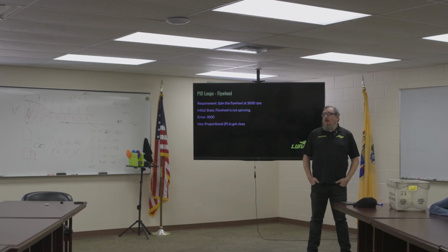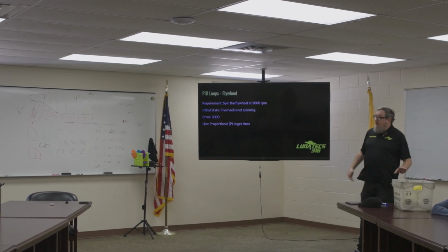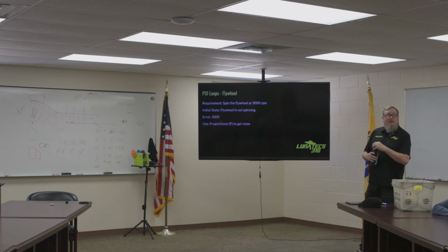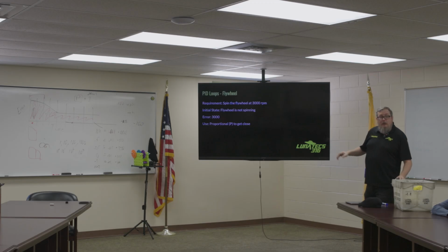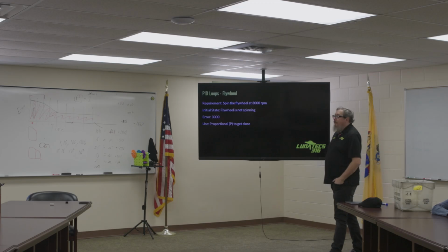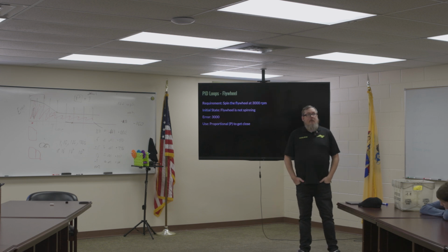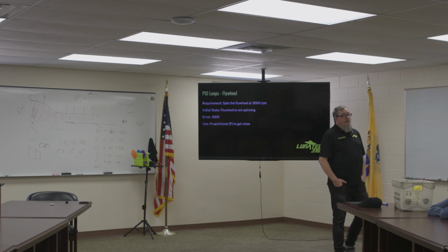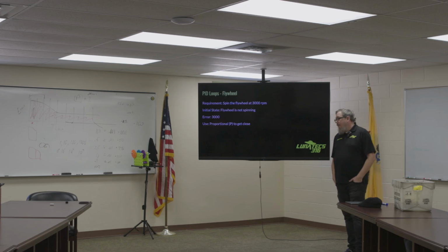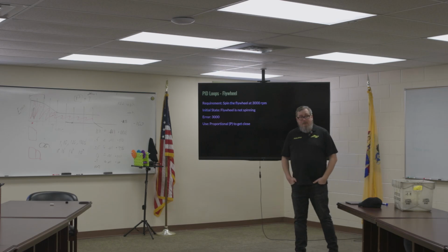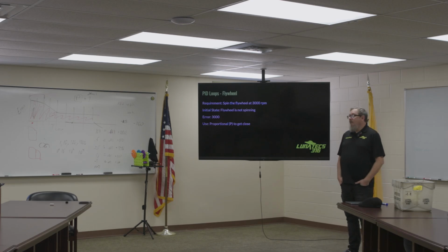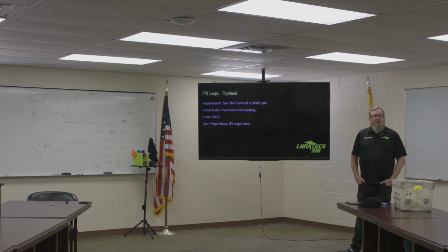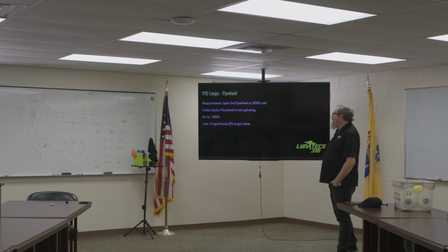Anybody who's not on programming? PID loops, how do they work? I just gave a whole lecture on it. They take proportional, integral, and derivatives, so let's just talk about the proportional. It's error over time, and it has a large error at the start, but it goes down as it tries to reach its goal set. And once it reaches that goal, it'll do a wave motion around it because it keeps releasing power, and then has to give power to it.